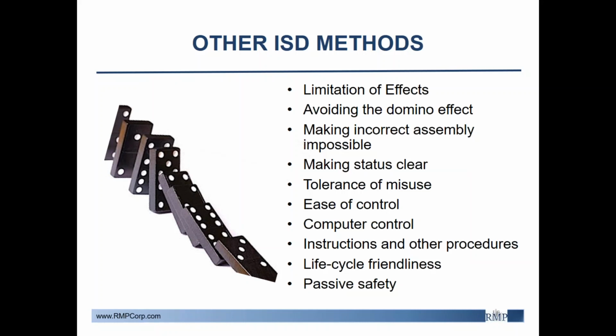Control of the process should also be simple and easy. It is recommended to emphasize control via physical principles like pressure and temperature gradients rather than with a bunch of extra unnecessary control equipment. Ensure that any computer software used to control the system is reliable and designed by someone knowledgeable of the process. Have standard operating procedures and clear instructions.